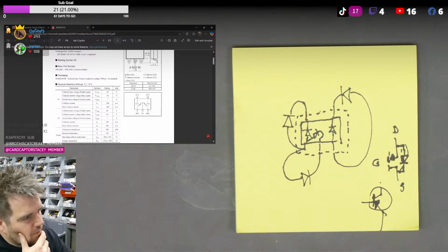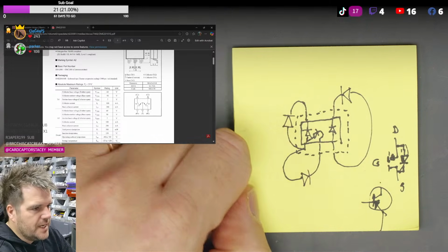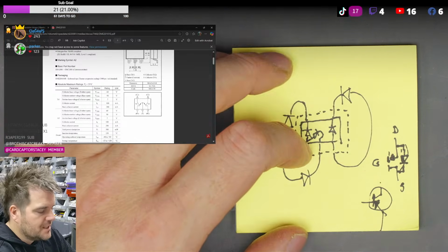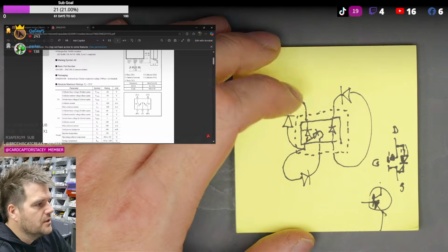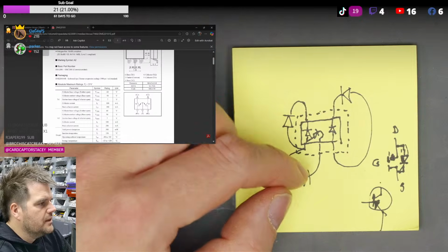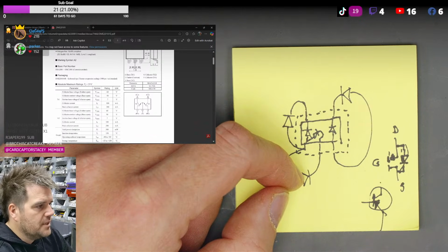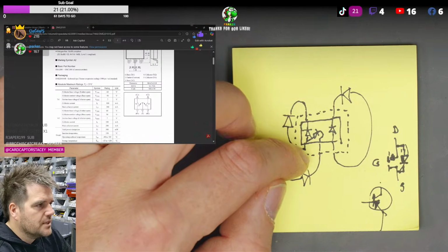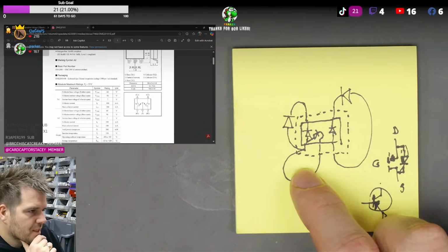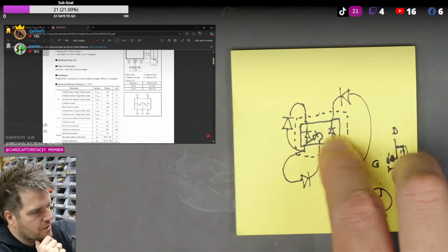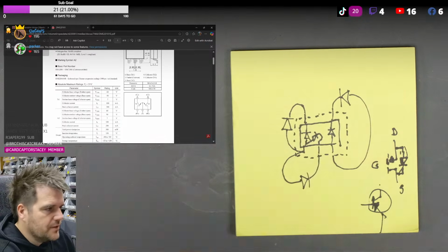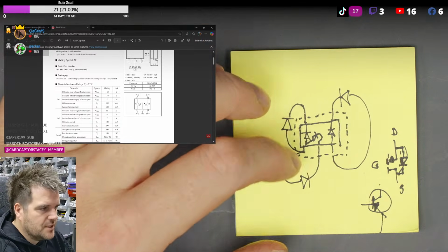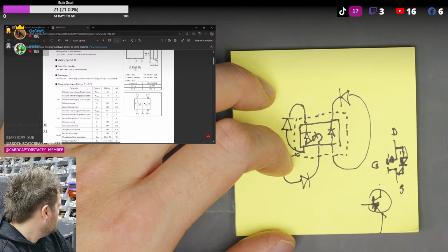I mean, you could have the most obvious thing, which is just literally 3 diodes in a package, and you've just done a Q designator. There could be nothing else in this package. It could literally be 3 diodes. But then you don't even get triple diode packages anymore, so you wouldn't even find this or know this. I'd maybe have to put this in a component tester and just test every combination of 3 pins to see if it picks up that there's current flowing through one. And if it notifies and figures out there's a transistor, that's probably what it was.